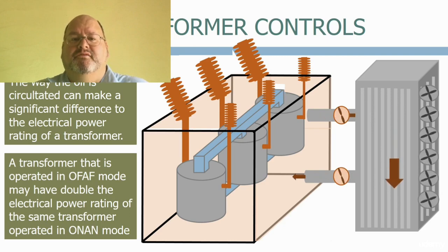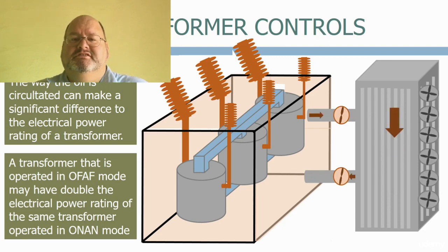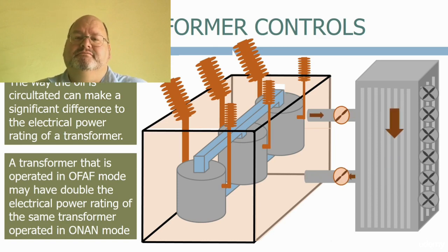We also need to be aware of the ambient temperature. When a transformer is being operated in hot countries, the ability of the cooling equipment to dissipate the waste heat is severely limited, and the transformer rating may need to be overrated at the design stage to supply the required load.